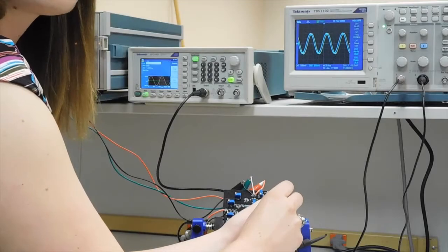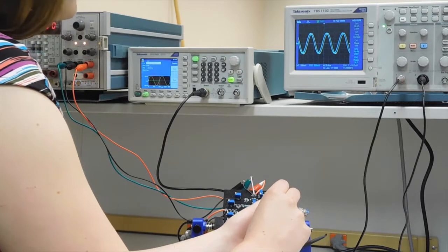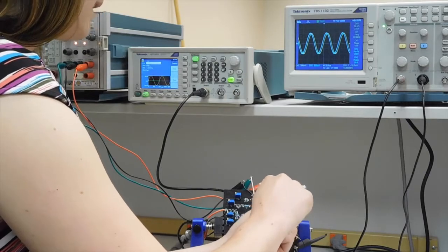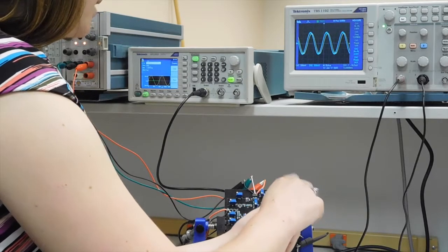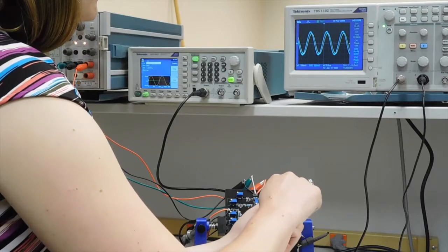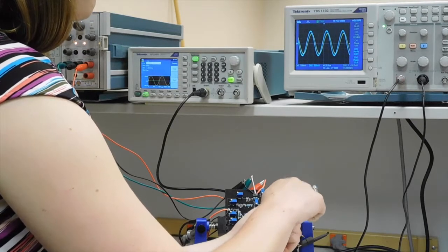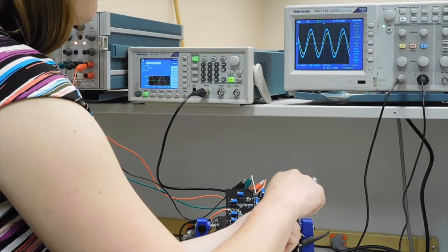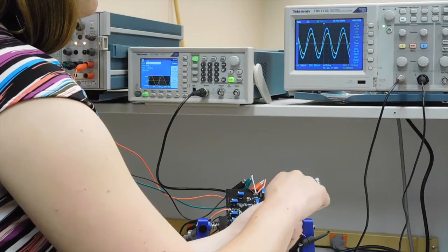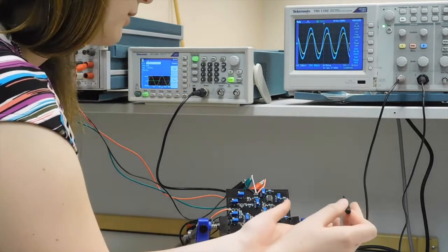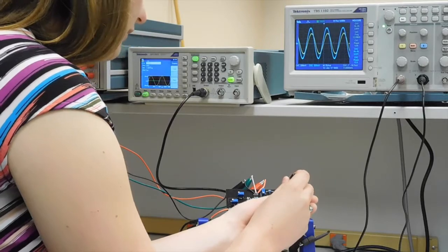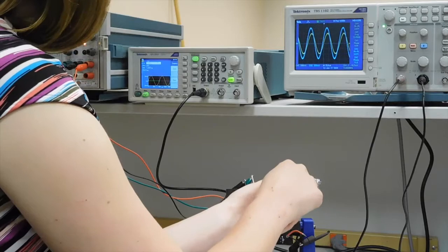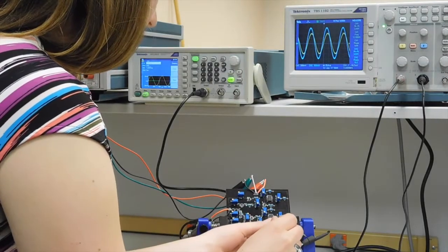I'm now going to show you how our third bandpass band works, operating at 13 kilohertz. As I increase the feedback resistor, you can see the amplitude of our wave does increase. As was true of all bands, if I change the feedback resistors of any of the other bands, there is minimal to no change to our output waveform, as expected.